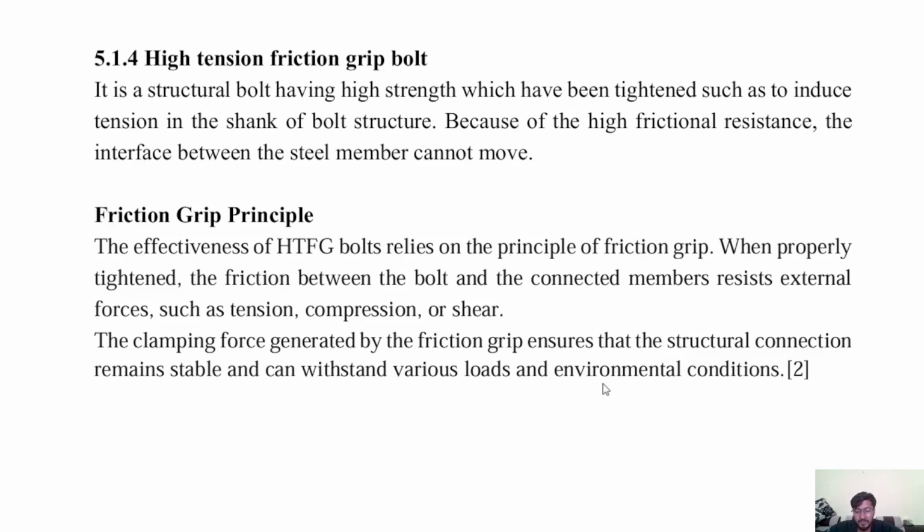They are particularly suitable for applications where reliable and durable connections are essential, such as bridge building, industrial structures, and offshore platforms. The main principle of effectiveness of high tension friction grip bolts relies on the principle of friction grip. When properly tightened, the friction between the bolt and the connected members resists external forces such as tension, compression, or shear.